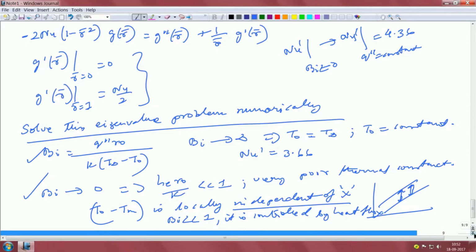So, we can see that when we actually did the uniform heat flux and the uniform temperature, we basically covered these two extreme ends. The actual situation is like a pipe in an isothermal fluid. So, in between Nusselt number, whatever may be your configuration, will lie somewhere in between. So, that is an important case to note over here.